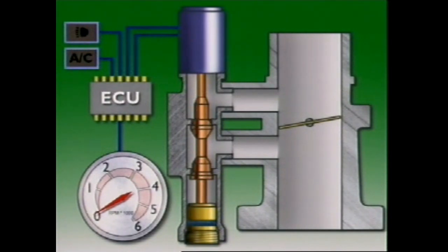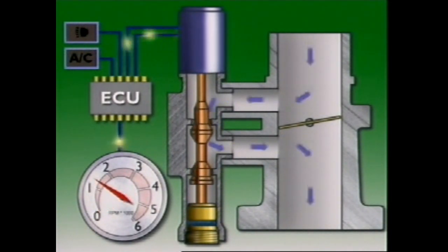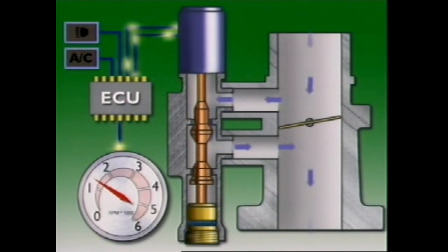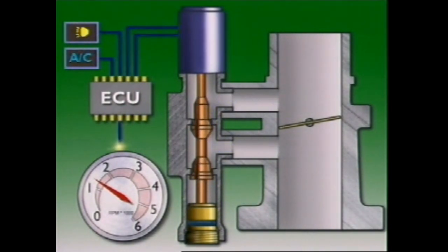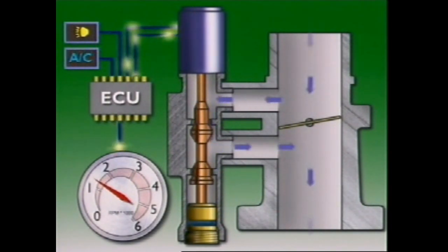Another method uses an idle speed control valve with the bypass passageway controlled by the ECU. The passageway is varied for cold starting and if the engine has extra loads, such as headlights or air conditioning. A predetermined programmed idle speed can thus be maintained.